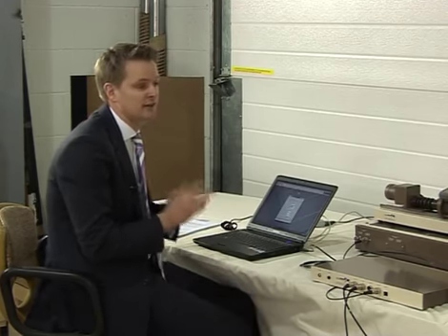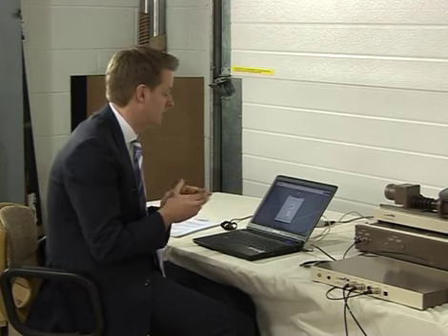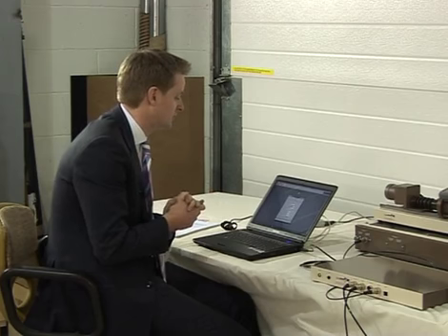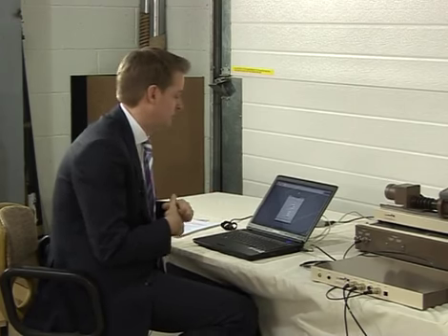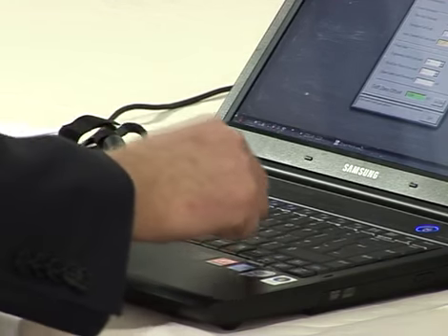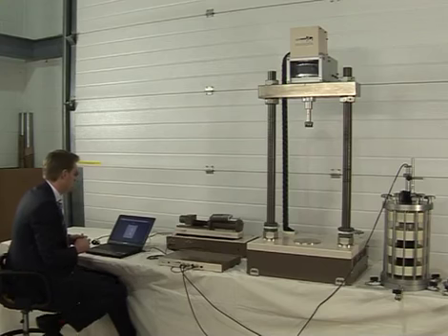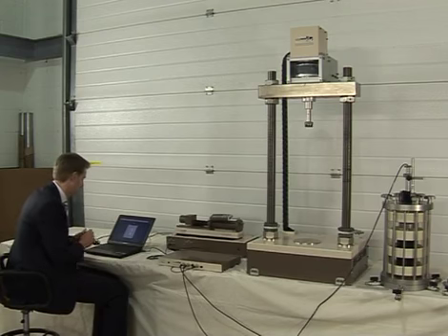It uses this value to calculate the maximum load available on that transducer. So not only will it give us the correct calibration, it sets some safety limits as well. So I have read that 22.377 is the transducer full scale output for this internal submersible load cell. So that must be entered here.